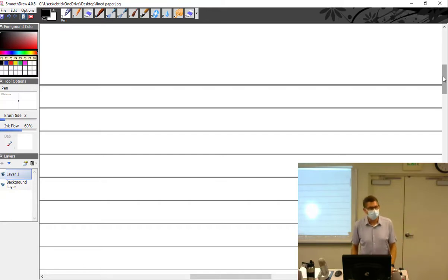Going back to that, till now, a good mechanic is saying, okay, it's time for your annual. I got to pull your battery out. I got to put it on a measured discharge. Some people don't like that still, but that's the right way to do things. By the way, in your battery manual, because you're thinking, well, how are you going to do that if you have your own plane and you're supposed to do a measured discharge? Who's got a couple grand to buy one of these battery things? It says right in there, just get a known load and do it. Get a light bulb or something like that. It's not a big deal. The manual literally tells you to do that.